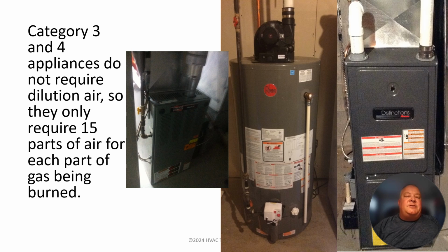I'm showing a mid-efficiency furnace on the left that actually has louvers in the door, so the air from the room around the furnace gets in there to supply the air for combustion. On a power vented water heater in the middle, right down by the gas valve, there are perforations around the skirting of the water heater, and that's where the combustion air enters that water heater.